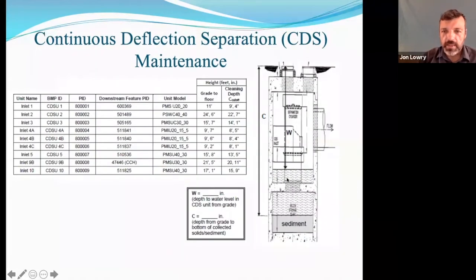The more difficult task is cleaning the sediment out of the sediment chamber down below. And so as a contractor, it's important that you know exactly what the dimensions and depth of the device is, and that when you're cleaning, you get all the way down to the sediment chamber. We have had instances where, as you can see, there's a little bit of a shelf here where only this top chamber gets cleaned, and then we go back to take a measurement and realize this lower sediment chamber hasn't actually been cleaned. So it's important to understand how to measure these devices.